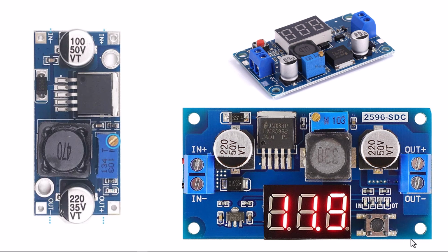The ones that I'm using are more like the upper one, but where you see those little rectangles of solder next to out plus, those are holes that go all the way through the circuit board, so you can actually put wires through there and solder it on the other side. So it's double-sided. I like the ones where you can solder the wires and then leave those terminals for something else. As long as you solder a wire to out plus, that's the same electrical connection as the terminal right next to it.